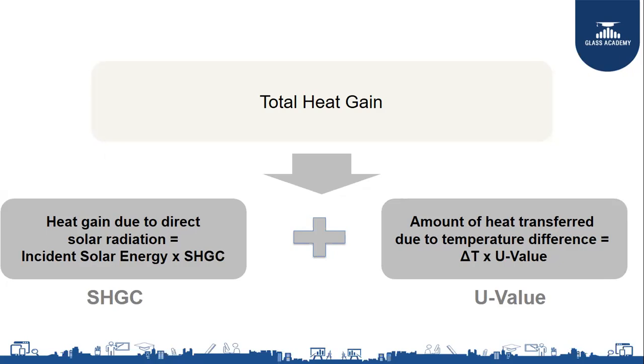If you observe in fully glazed office buildings, if they switch off the AC, or if there is a current shortage, in the morning when you go and switch on the AC, it takes a lot of time to cool down that area because of the heat that has come inside. So this is one area where if you use low U value products, the amount of heat coming inside can also reduce. So this is during the night time and also during the daytime. Whereas your solar factor is very important in terms of the daytime heat reduction.